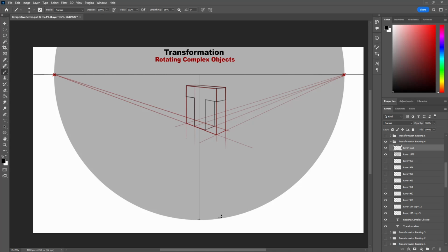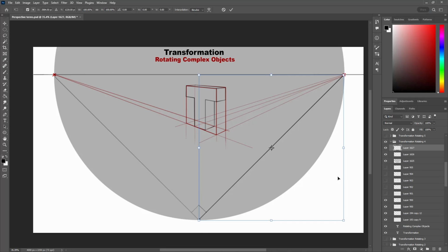Let's choose the one in the center to make things easier. We connect the 2 ground lines between the stationary point to the vanishing points with 90 degrees in between. Now to get the measuring points, we copy the ground line length all the way to the horizon line. Wherever this line ends is the measuring point from one side, and the same goes for the other side. Since we picked the stationary point in the center, both distances will be equal.